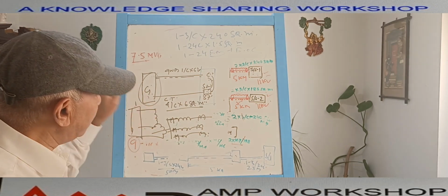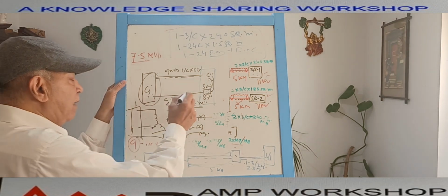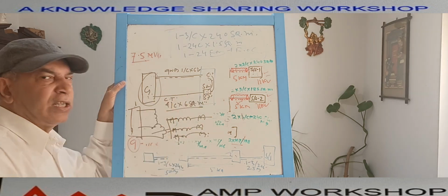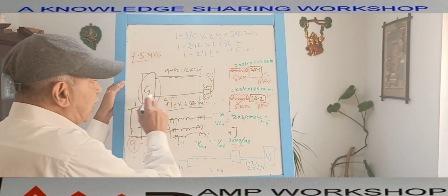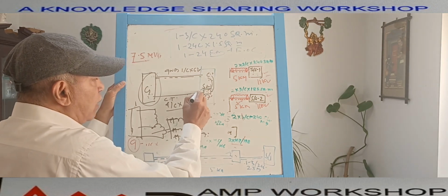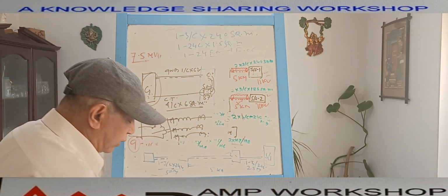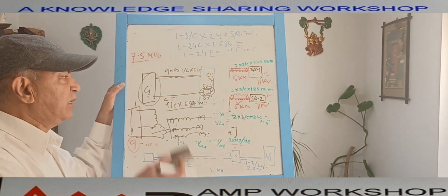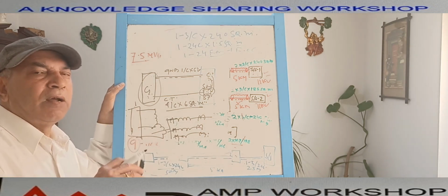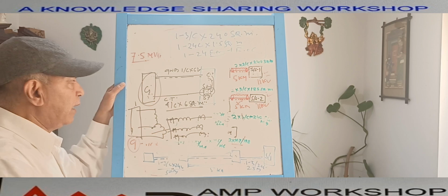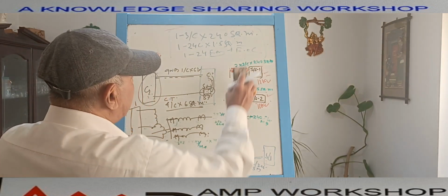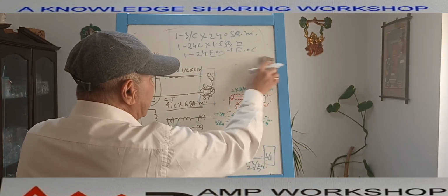In addition to this, there is the line PT, for the synchronization purpose. When this generator power comes to the switch gear, we have to synchronize the switch gear breaker. How do we synchronize? We synchronize the generator PT and the bus PT by sensing this PT supply. We have already discussed how the generator is connected in the generator protection.